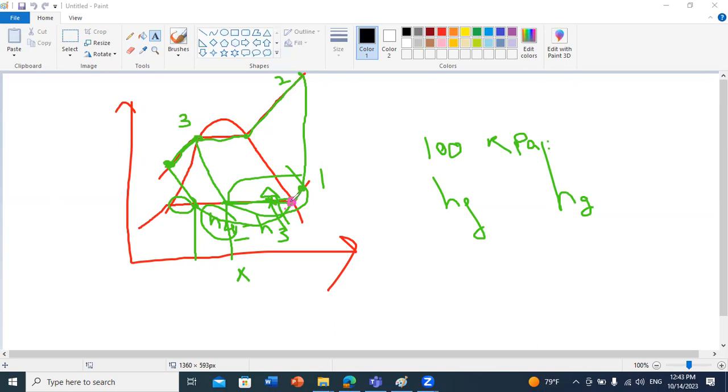In this case, the inlet of your compressor will be a saturated vapor, and the outlet will be superheated vapor. While when you talk about a pump, you should have an inlet of saturated liquid in order to not harm your pump. So the pump and compressor work in different regions. A pump is designed to work in a liquid state, while a compressor is designed to work in vapor state. Okay, thank you. Welcome.